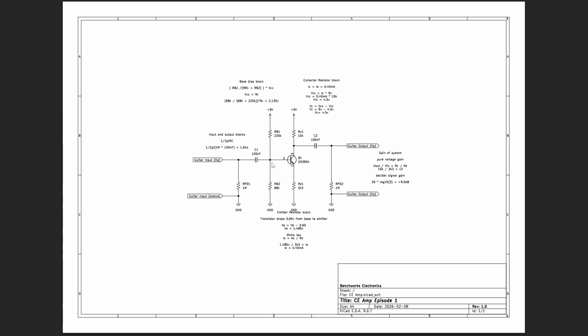And the way we do this is we pick a voltage at the input that will end up setting our midpoint at around, or as close as you can get to, 4.5 volts, or whatever your input voltage is divided by 2, the midpoint of your power. So it works out with this circuit, if we use 2.1 volts at pin 2, the math at the bottom here will explain the math at the top.